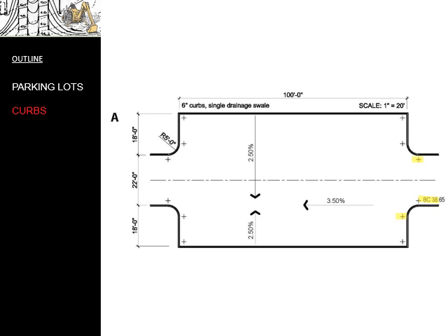For the one across the parking lot, you will simply use the slope that we've given you that runs across the parking lot. That's because this yellow line is the line of the valley or the swale that runs along the entire length of this parking lot.